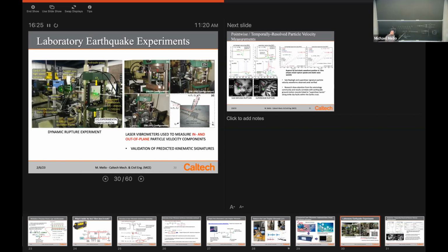And I'm showing you that you can actually use these vibrometers in this very strange configuration that they don't even tell you about when they sell it to you, okay? Everybody's talking about using these vibrometers as, you know, U3 dot, right? Normal motion. But if you get that little retroreflective tape there and you come in at those beads, those little glass beads that sit on this tape, they do a phenomenal job of scattering light, and they scatter light back that way too, okay?